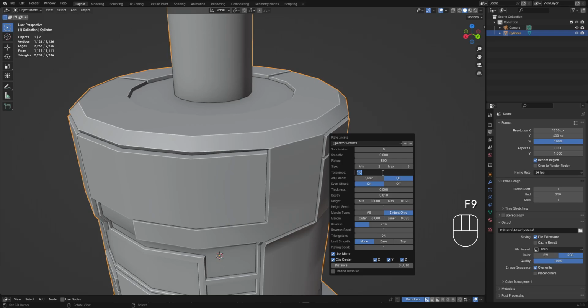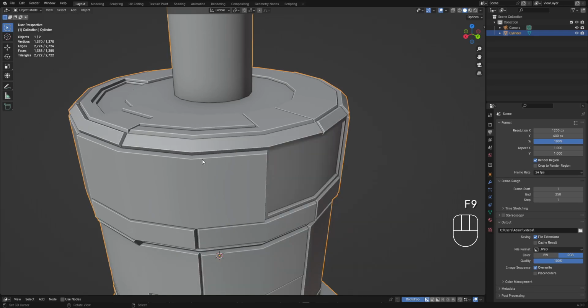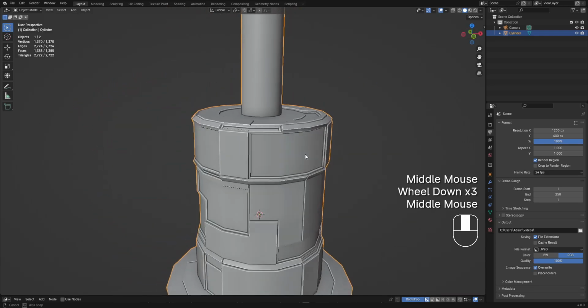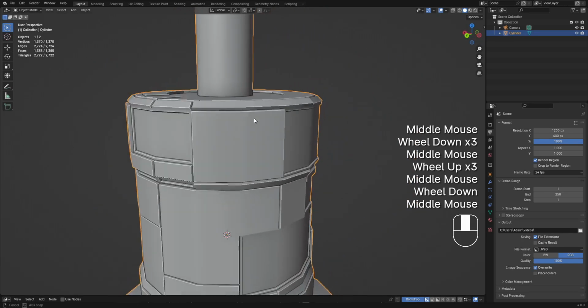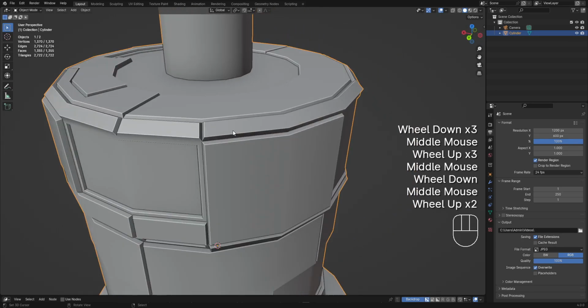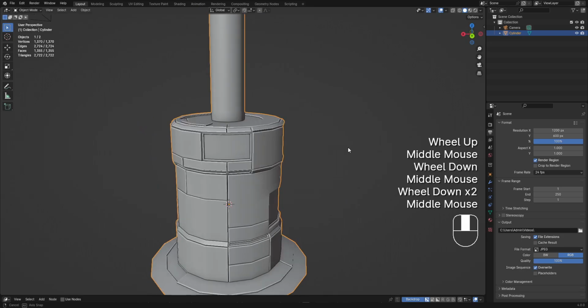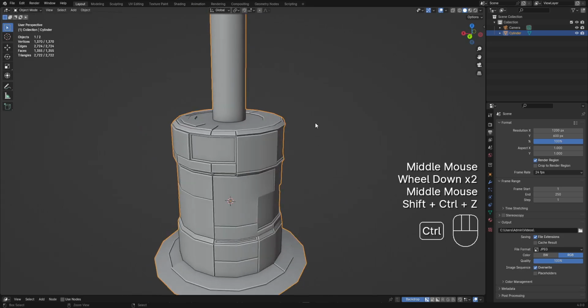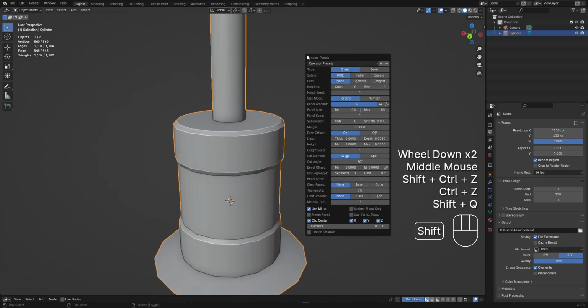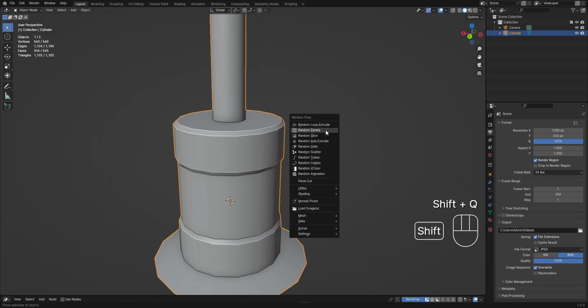So for example, if I lower this to 0.5, the plate insets cannot go past or wrap around the sharp edge. So you can see that there are cuts here. Kind of works like plate inset, random panels, and then using the split or wrap in the cut method. Okay,